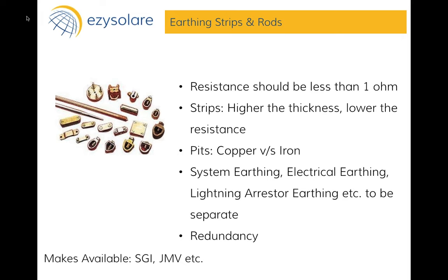Thickness of the roof essentially determines whether you would have to have a ballast foundation or whether you can dig into the roof a little and have a J-bolt inside the roof or a Hilti inside the roof. This is particularly even more important when you have a shed-based roof and you need to make penetrations in the roof. I cannot get into all the details because that might not be in the scope of this webinar, but it suffices to say that the single most important thing is the location and the second most important thing is the type of roof when determining the structure. The height of the structures and the wind zones would also determine what kind of strength you would need the sections to have and accordingly what weight the structure would be.